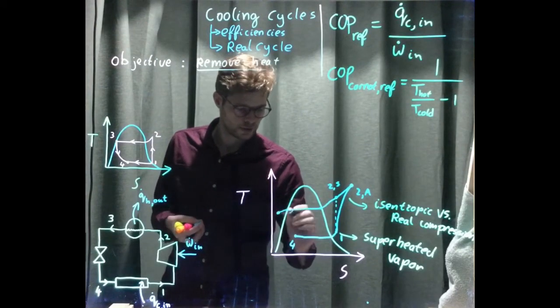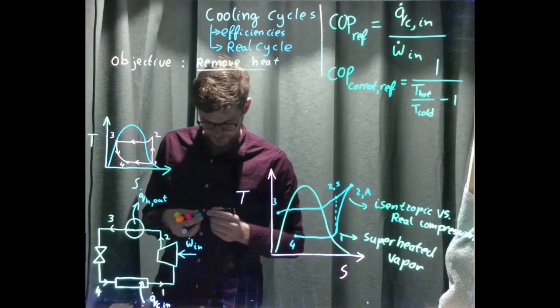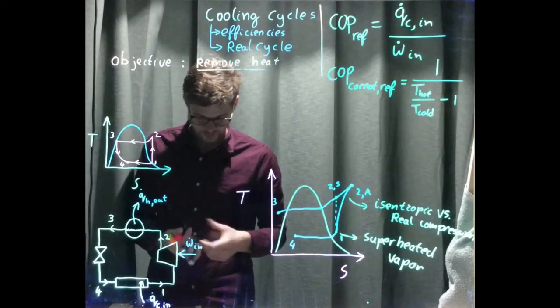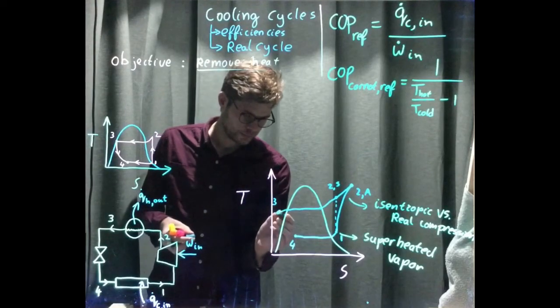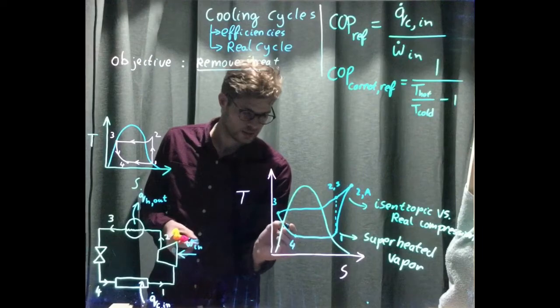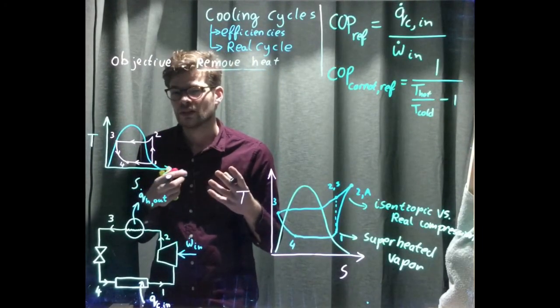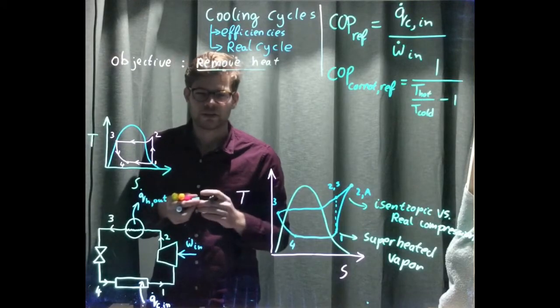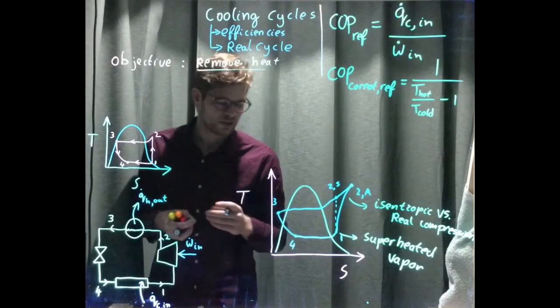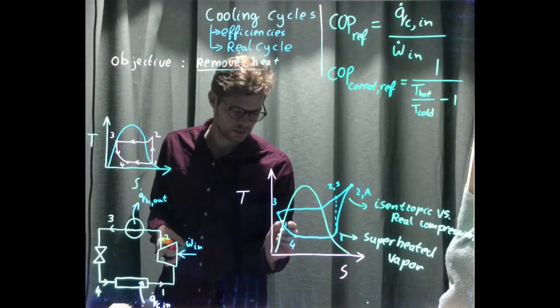So the fluid may become a compressed liquid. Point 3 over here, and from there we go back again to point 4, isentropic. Of course, isentropic in real life is probably not isentropic. It will always require some energy, but these differences will probably be negligible.